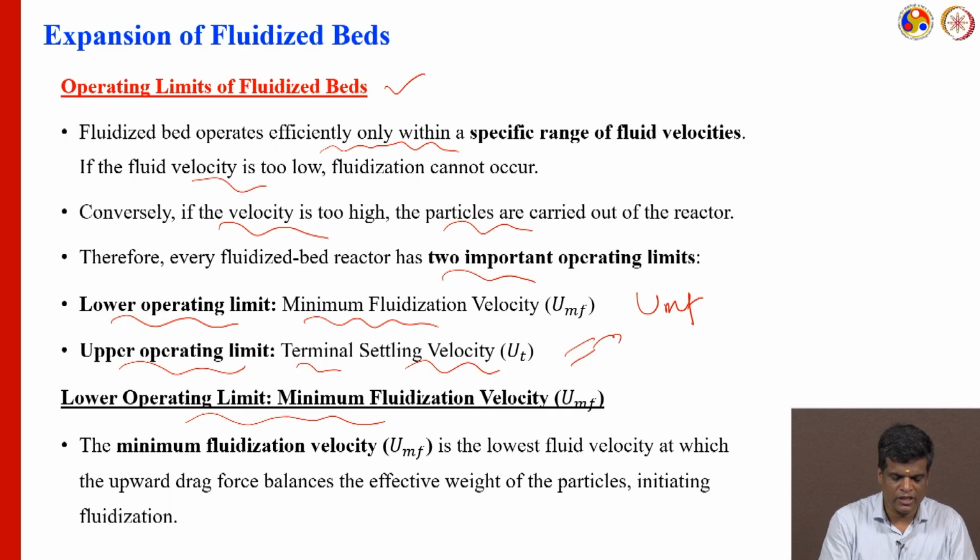So, what is the minimum fluidization velocity? The minimum fluidization velocity is the lowest fluid velocity at which the upward drag force balances the effective weight of the particle, initiating fluidization. To initiate the fluidization, that point is called the minimum fluidization velocity.